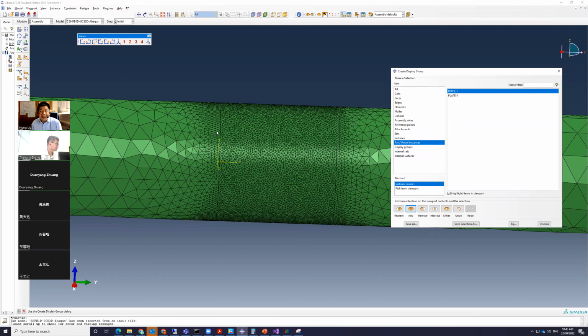We make sure that on the two sides of the contact surface, the elements have almost the same density. This is important for the accuracy of the contact calculation. For our contact calculation, we use the penalty method. The contact here is the surface between the bar and the rock. So we finally discretize the contact between the tetrahedral elements.